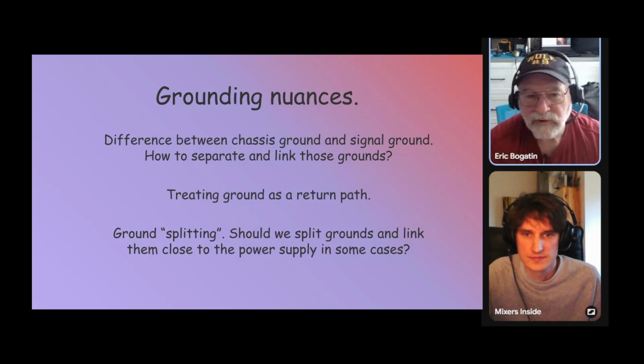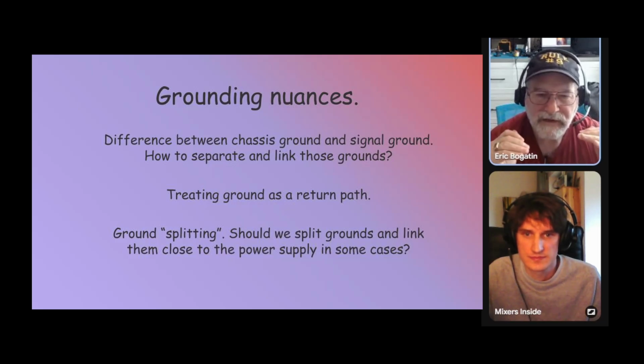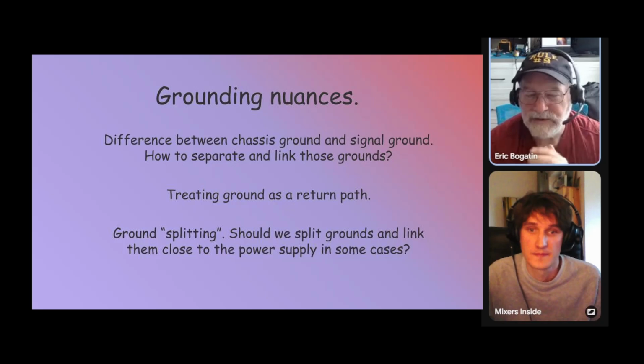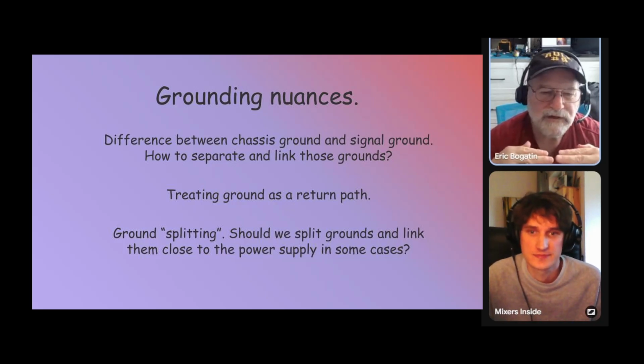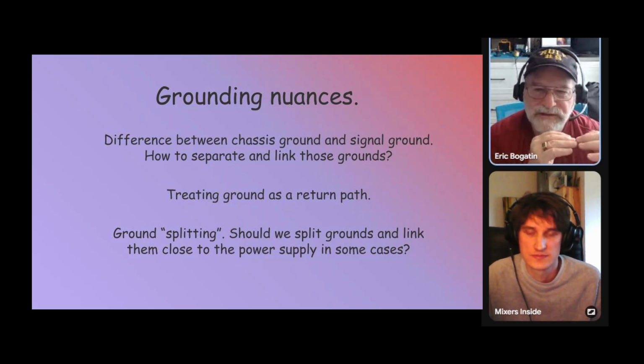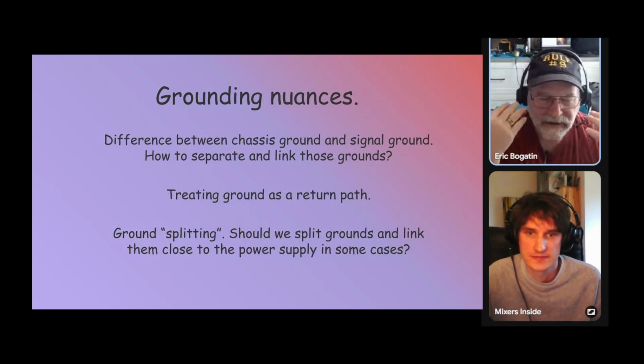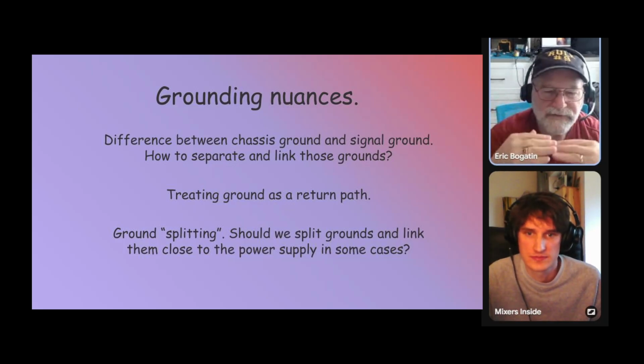And if you have an amp of current, that's a millivolt. And so you could have a millivolt of noise from one end of your reference to the other end. And if your signal from the microphone is a couple of millivolts, you can see a pretty large amount of noise contributed to it. And that's where you want to minimize the sharing of the reference conductor with the return conductor.